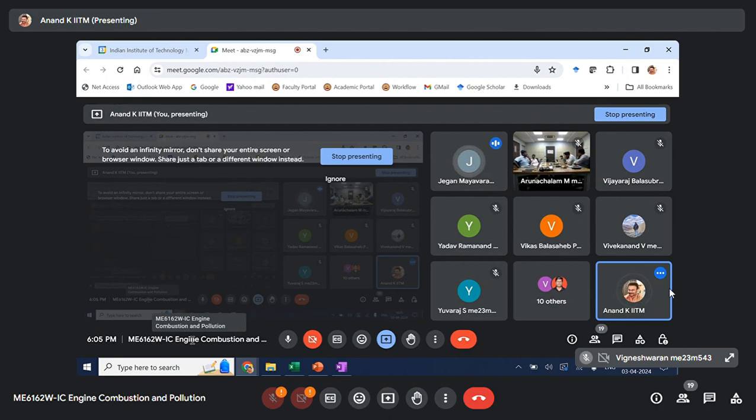No, sir, for that one, the control system networking is common for all the units, because we have minimum 6, maximum up to 14 cylinders. Normally we have a common engine control unit, which commands each unit, and each unit has its own control system. So when one encoder gives an error, the system will understand the second encoder as having the same error, although the second encoder is working fine.